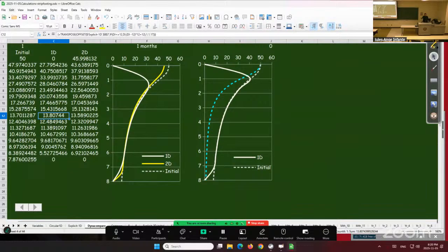One of the things that you discover early on when you look at Boussinesq is that there's no closed form solution. If you want to do axisymmetric or 2D, 3D, you have to be aware that there's no closed form solution available to express the state of stress anywhere below a circular loaded area, except directly under the center or directly under the edge.